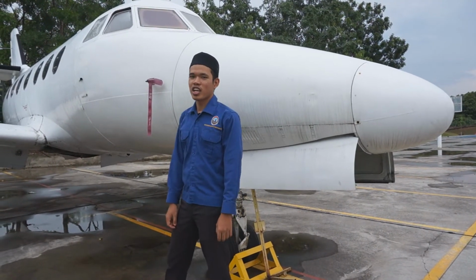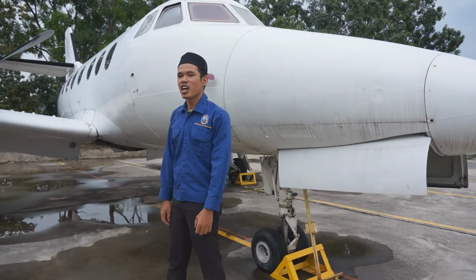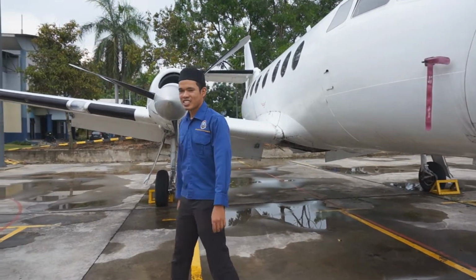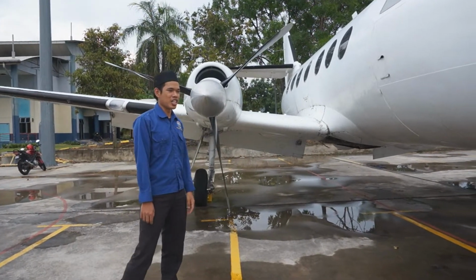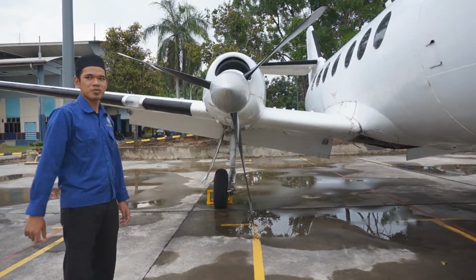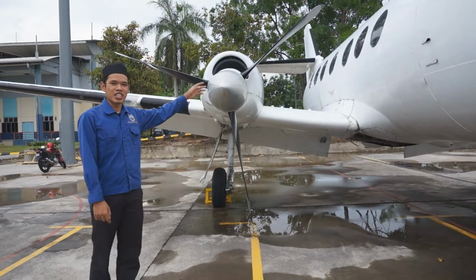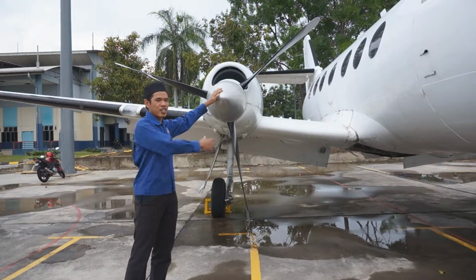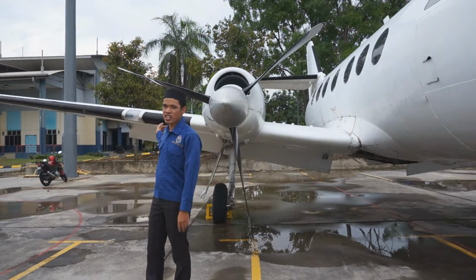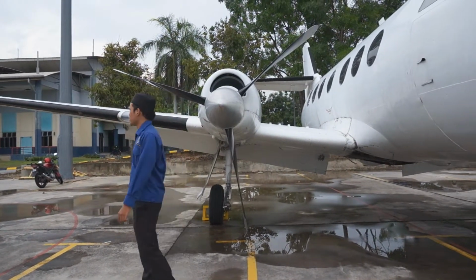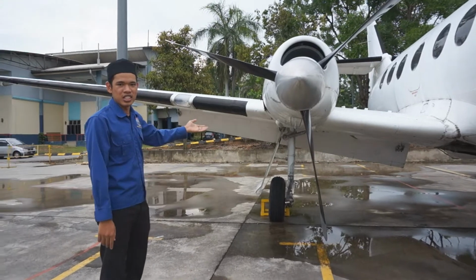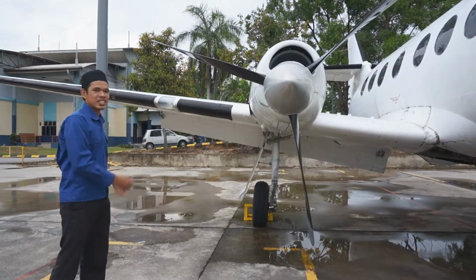Thanks to our friend for the explanation about the bending. Now I will explain about the application of the bending to the aircraft wing. On the aircraft wing, we experience two main forces, which are the upward force and the downward force. The downward force is caused by the weight of the engine, while the upward force is the lift force acting uniformly below the wing.